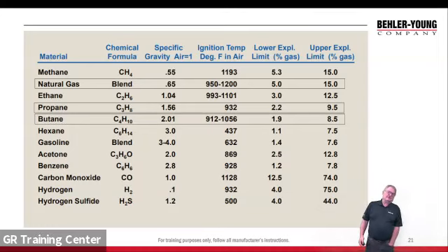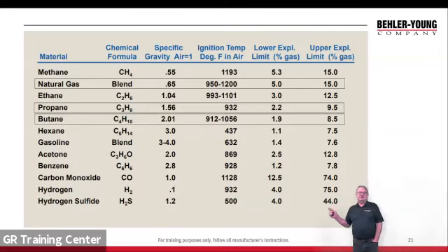Butane, I'm going to throw out there because we do use that as a refrigerant actually in some places. So we want to take a look at that. So butane, like what you have in your lighter. The LEL, or lower explosive limit of butane, is only 1.9. Okay, so it doesn't make a great heating fuel because we're starting to get to a very dangerous point with it. And its upper explosive limit is 8.5%.